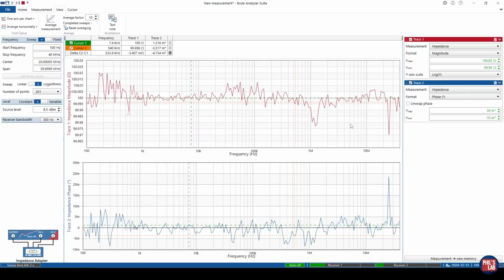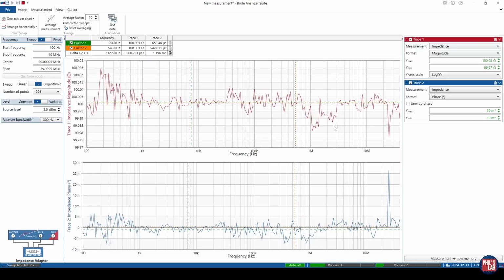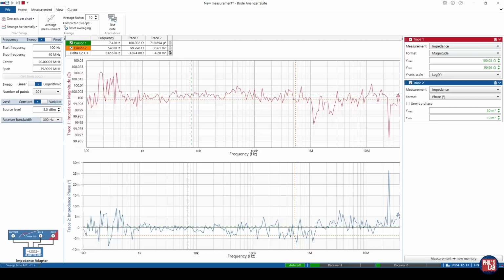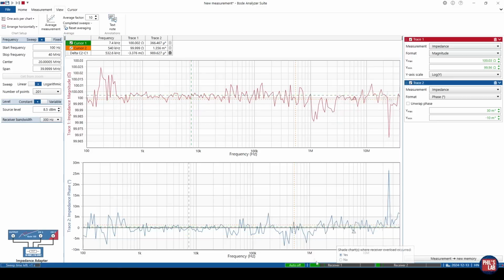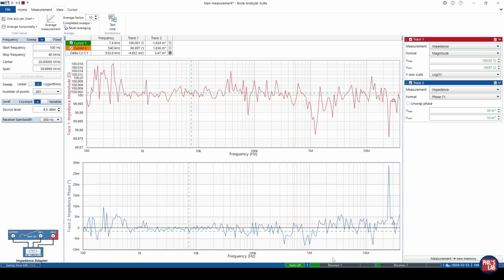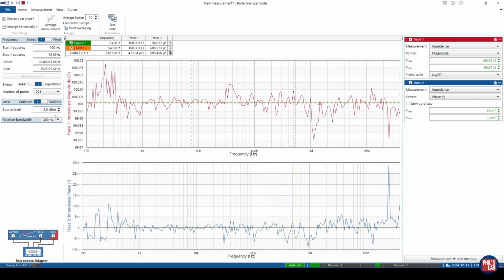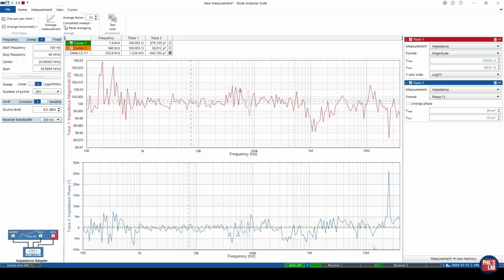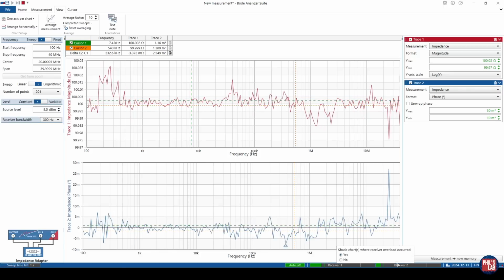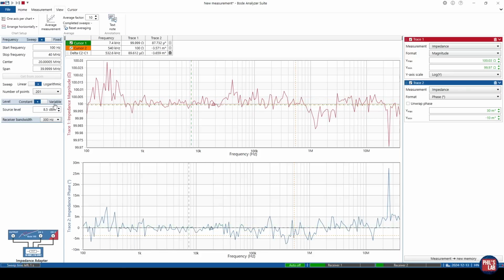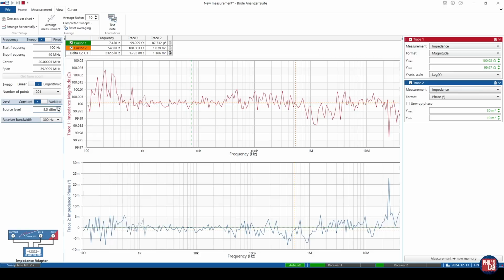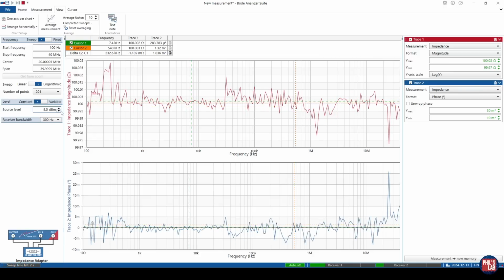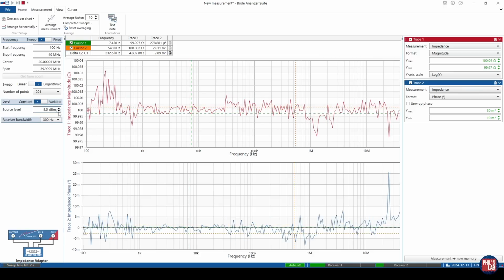Another thing to verify is what your receivers, your channel 1 and channel 2 receivers at your inputs, are receiving, and we can see that on the bottom side of the screen. The green bars show the receiver indicated signal strength that is being received. So we've arbitrarily set a signal source level of 8.5 dBm, and we're getting a third or even less signal strength. So we could increase that, but keep in mind it's not just about the receiver signal level, it's also about overdriving, exciting any nonlinearities on our measured components. For now, we'll just leave this.